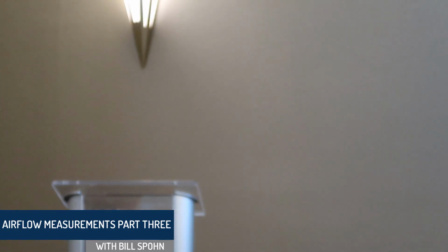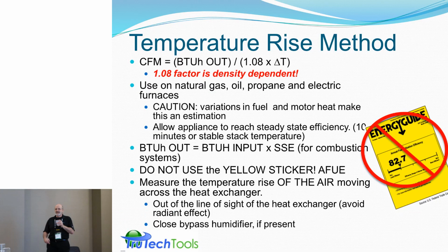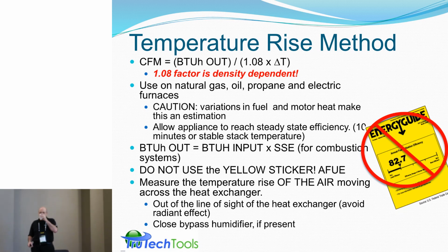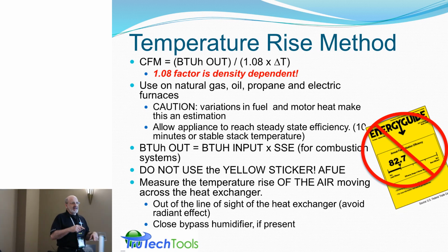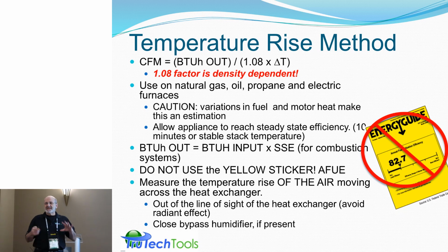Okay, moving on to the temperature rise method. I think I picked that first because it tends to be the most popular in the educational setting. You basically rewrite the sensible heat equation to get CFM. And as everyone knows who's in education, watch your units of measurement.